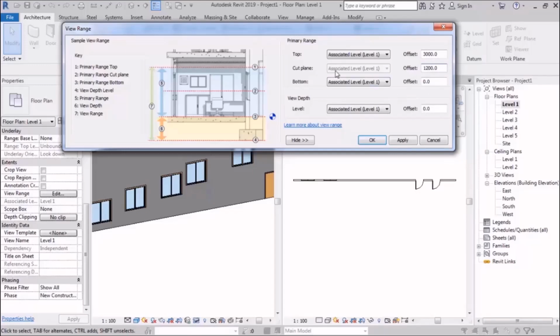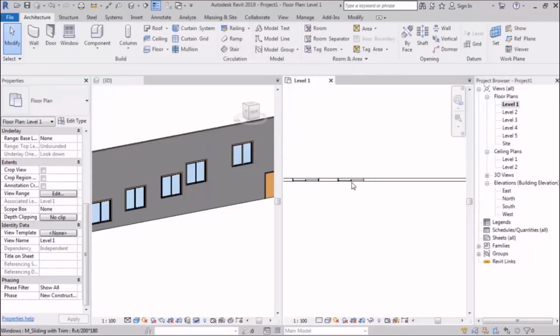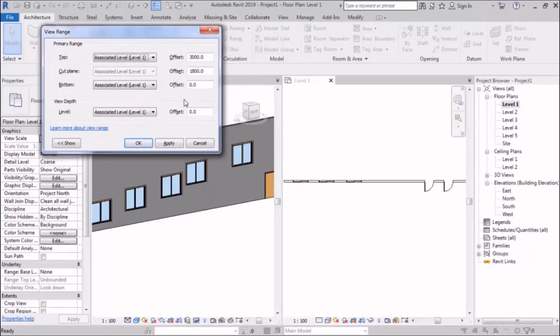Alright, now we know that the height is 1.20, so these two can be seen, but the rest of them cannot. So I click on VR, and that was 1.70, so I write 1.18 here. And when I apply, what happens? The third one appears too. Now the fourth one, that was 2.14, so I enter 2.15 here.